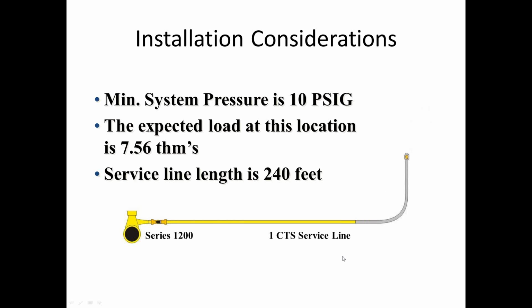And so as we're looking at this, we want to make sure that it's not necessarily how quickly, but how far you open that valve. If you have a procedure where you don't want to trip the valve, in other words, it's not part of your practice or process to trip the valve to verify its operation, then you'll want to give instruction on how far that valve should be open during this operation so that it doesn't trip.